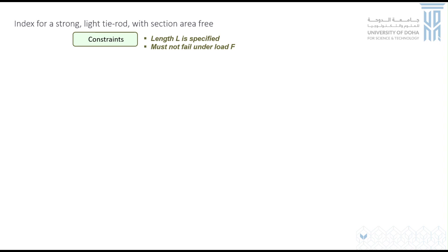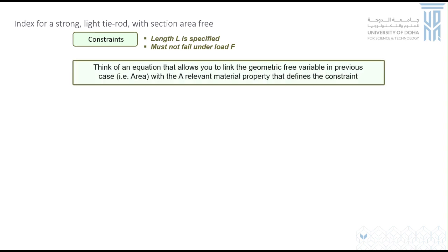Now think of an equation that allows you to link the geometric free variable, which in this case was our area, with a relevant material property that defines the constraint. Stress equation. Come on, guys. Basic force over area, isn't it? So it's linking your constraint, force, with the free variable, area, right? So stress is the basic equation that you can use in here.